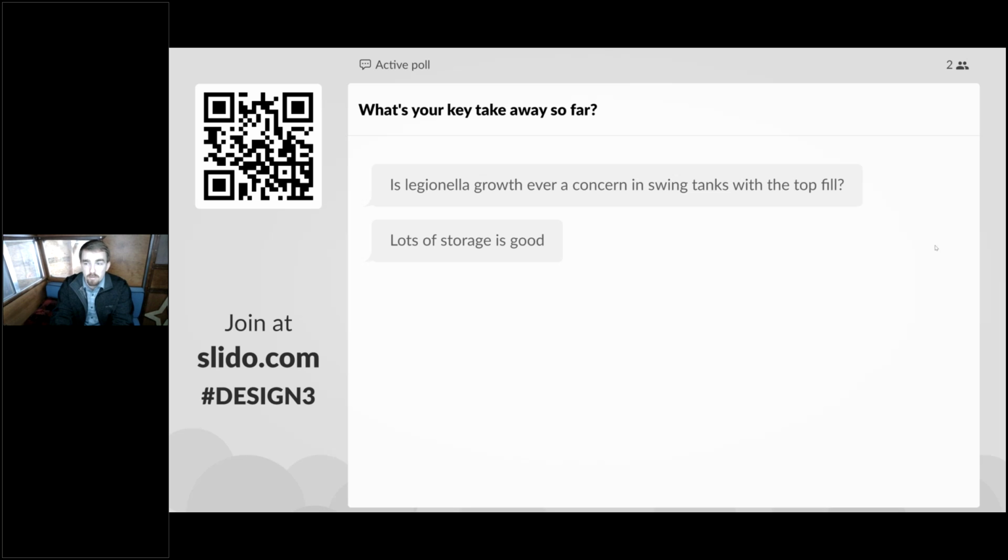Jackson uses parallel temperature maintenance, so they're actually heating that temperature maintenance tank up to 140 with the heat pump water heater, rather than relying on that swing in temperature to provide a buffer as the usage from the primary storage comes in and heats that up from a cooler temperature. So I hope that answered your question. Definitely send some follow-up in the chat, or even in here, if you want any further detail on that.